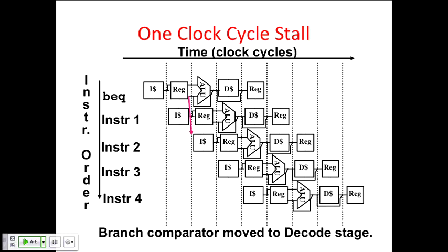Now what might happen is this instruction produces a value and I forward it to some other instruction. But notice when I forward the values, I still haven't written it to the register file. That's just an early, sneak look at the value when it will get there. So I haven't changed the value in the register file, and it's okay to blow things away. The hard part would be if you actually did write to the register file or the memory, then you'd have to worry about undoing it. But we designed the pipeline so that won't happen. Great question.